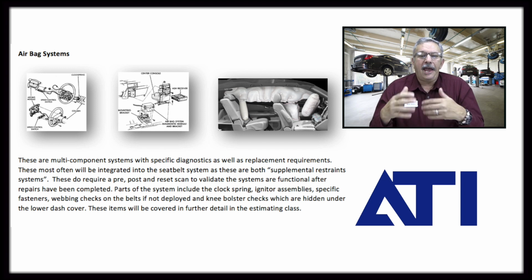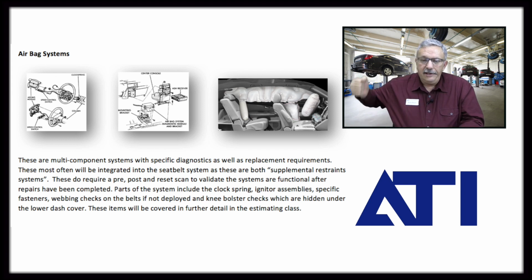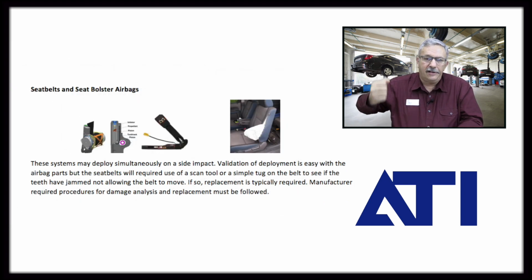So knowing how the systems are diagnosed, again, the pre and post scans are really important. Something as simple as, can I pull the seat belt and does the retractor work? That tells me whether it exploded or not. If I've got a deployed airbag, that seatbelt should still be locked.